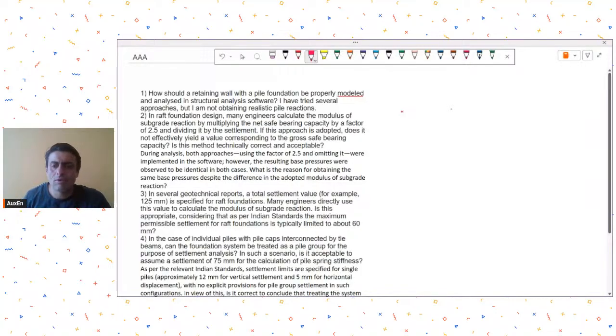Now in plan view, it may look like this: this is your retaining wall in plan view, and you have got the toe portion and the heel portion. Now at certain distances, at whatever interval you come up with, you can provide these types of piles. These piles can be distributed along the length of the retaining wall at whatever design interval.